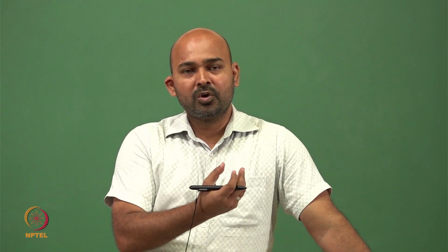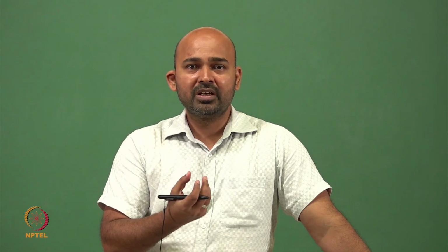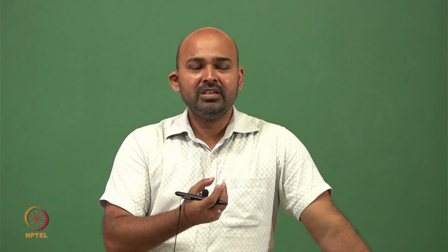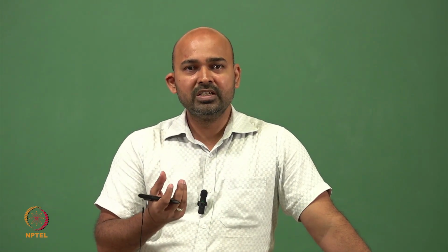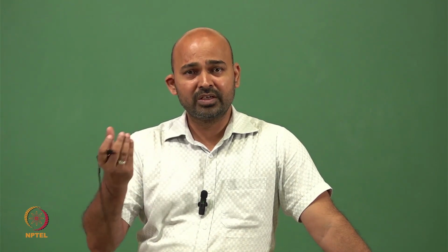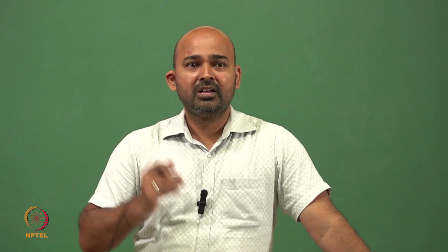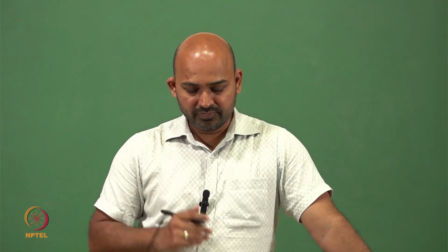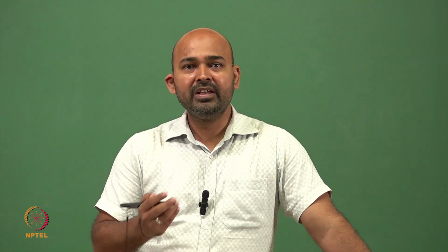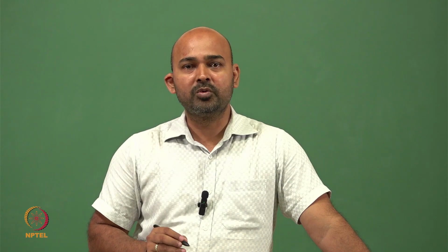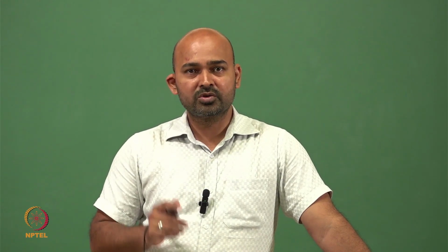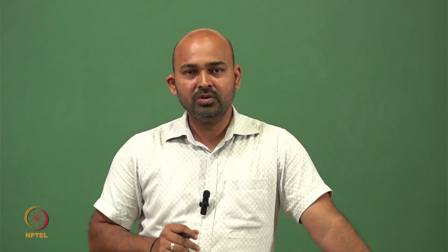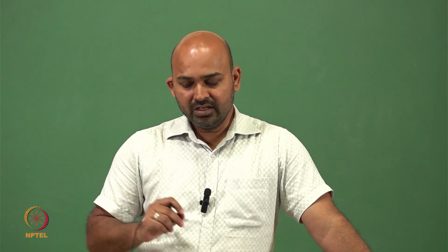One photon gives rise to one EH pair, or electron hole pair. This one EH pair gives rise to two EH pairs, 2 gives 4 and 4 gives 8, and this is like a geometrical series. So we get at the end a very high current in the output load, which is the R load. So one single photon gives rise to a significant current in the output load.